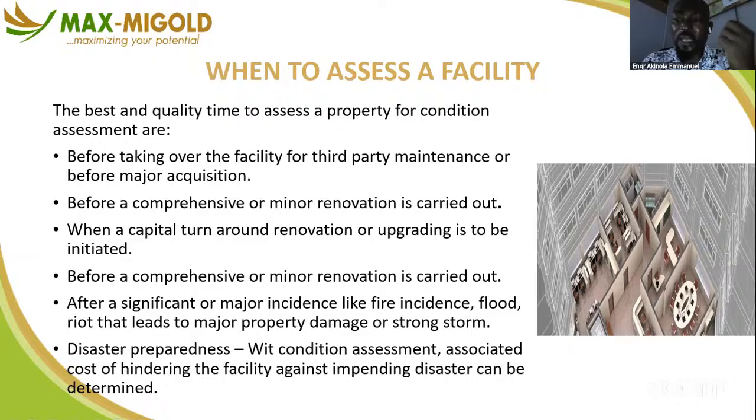Or possibly Lagos State Weather predicts that there's going to be heavy rainfall for a complete 7 days, and you know that there could be flood. Part of the assessment you need to do is to check that all the drainage within and around our facility is adequately flowing in case the rain starts.